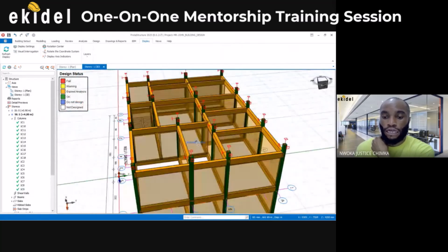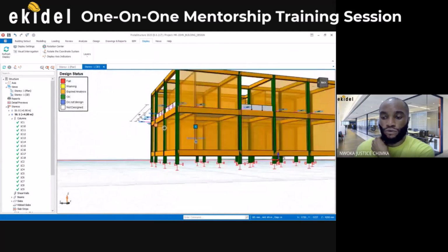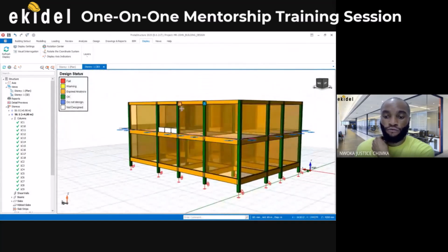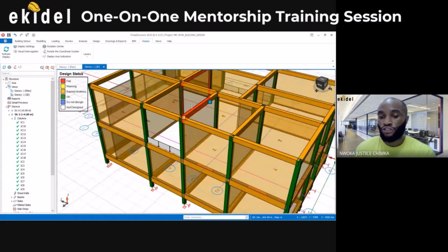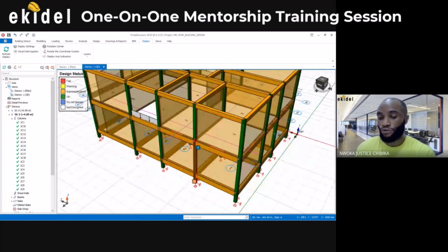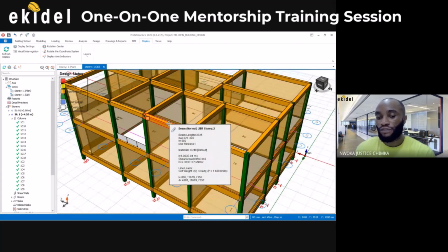Now that they have known the sizes that they are okay, we can now choose to run a new design again, for this not to show expired again. Understand? To run a new design and for now move into our foundation. But note, it is best you check all the beams. For the columns, you can do the ones that just failed. But for the beams, it is best to check all of them, even if they don't fail.